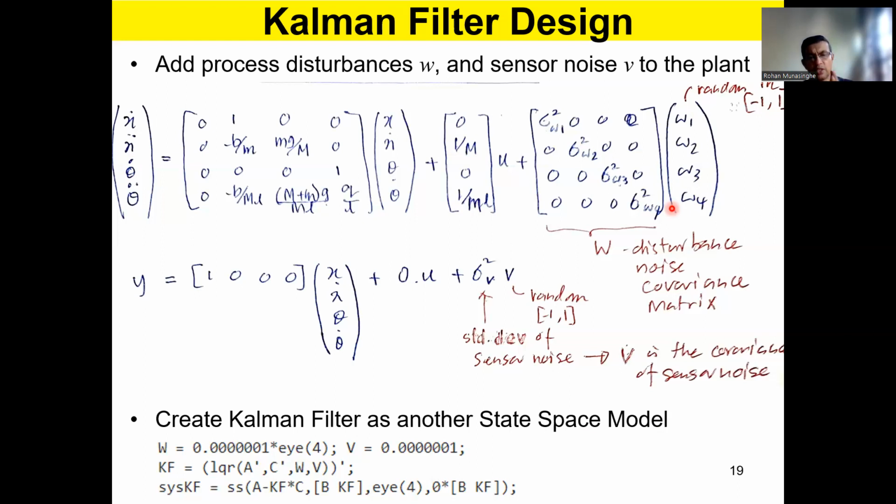If you just follow x dot equals Ax plus Bu, right, you will see it's different from the actual states, because there's always something that is unmodeled, right? That is what's called the process noise. You need to capture this one. Right? Kalman filter allows you to capture this one. If you know about the process noise, this is nothing to do with the sensor.